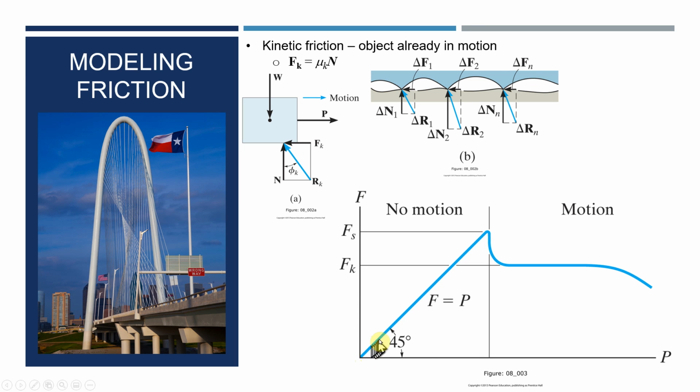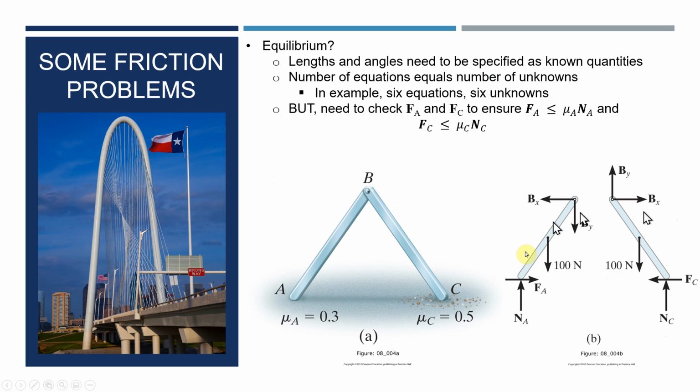That frictional force is going to be proportional up to this point at the top, mu s N. And then it goes to mu k N. Mu k is generally less than mu s, and it's flat. And what happens out here at high forces, anybody's guess.